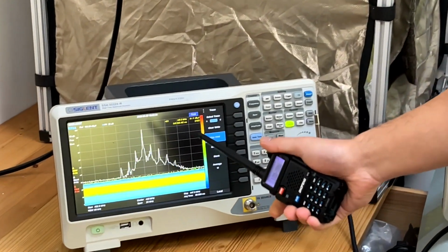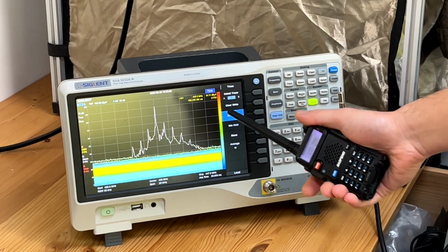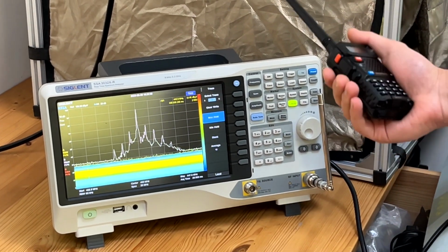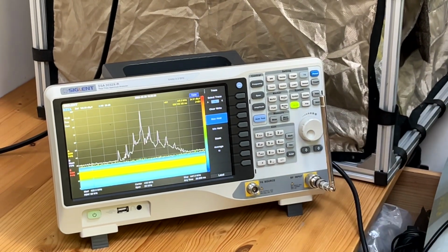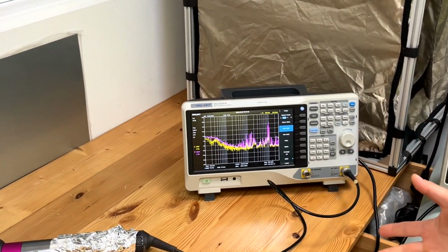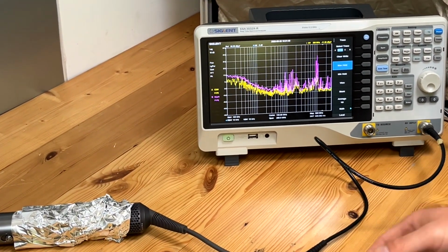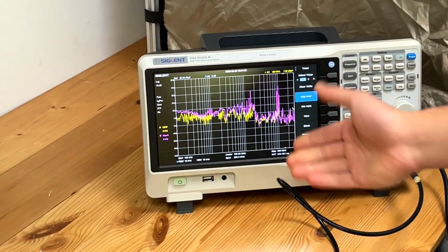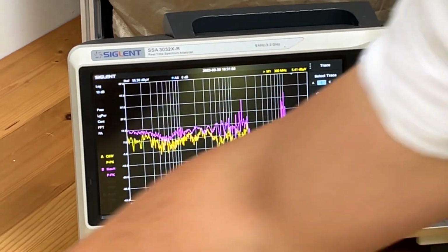For example, simply a walkie-talkie creates what we call narrowband noise source. And if your system or product is not designed against this type of noise, your product may suffer issues as what we saw previously. Or in this case, an electric motor typically will create noise in the lower frequency range, normally between hundreds of kilohertz all the way to megahertz, such as this. In a higher frequency range, typically 80 or 100 megahertz above, we'll see coupling mostly through radiation.